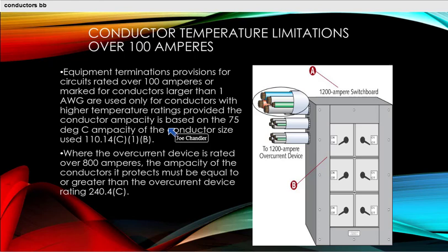Most of the wire we see is rated 90 degree C. So really, our ampacities of our conductors have to be based on, again, that weakest link. So probably 9 times out of 10, it's going to be out of the 60 or the 75 degree C column, depending upon all the terminations that fall within the circuit.